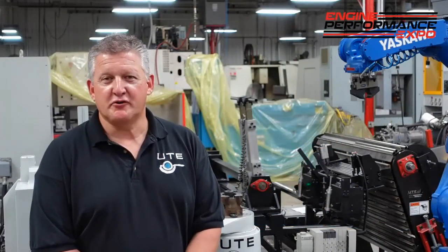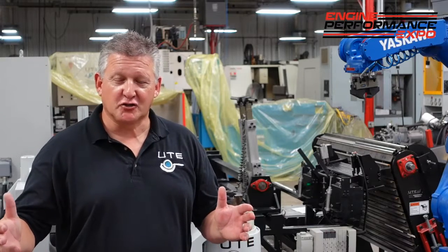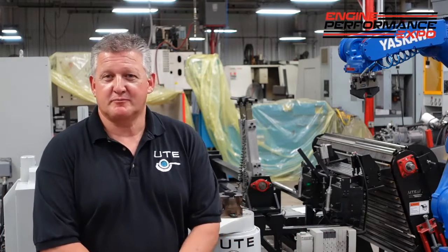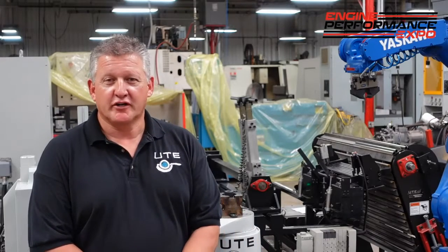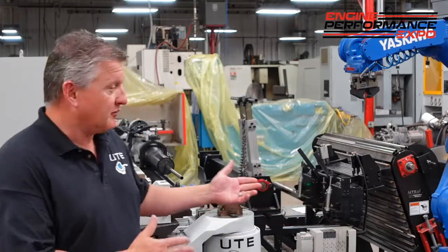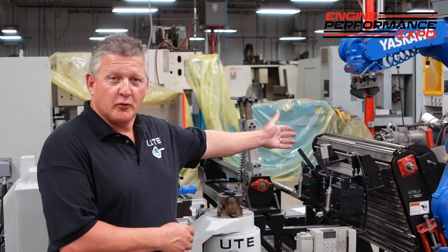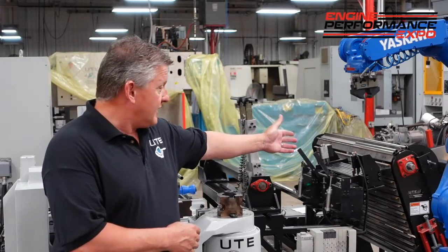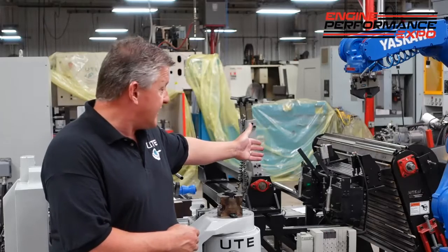Previously we showed you how to bend a tube, measure it in the measuring center, correct it, and then your second part is the perfect part. Now we're going to take it a step farther and automate the whole bending process. Here we have an automated tube bending work cell. We have a bundle loader over here. We can put a whole bundle of tubes in. It separates them out and puts them in each ramp. The ramp escapes one tube at a time.